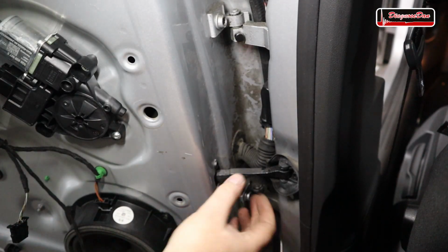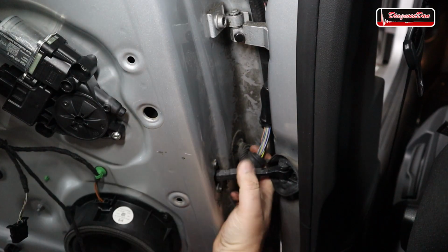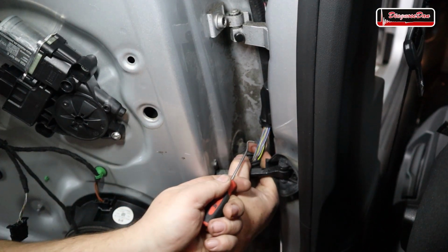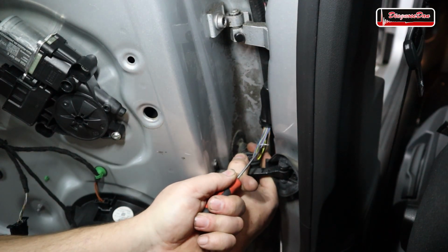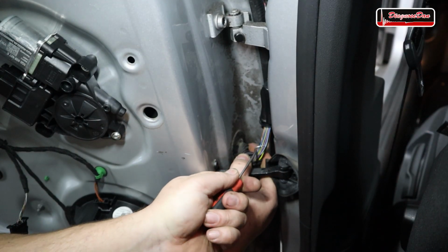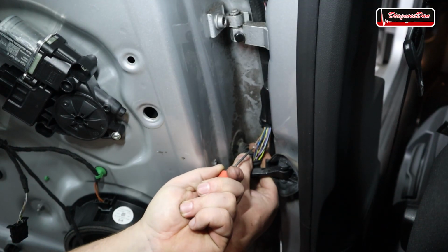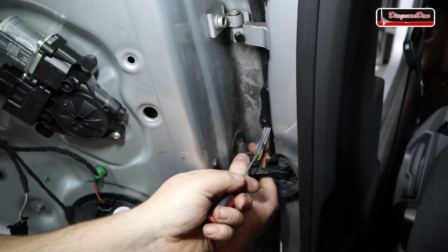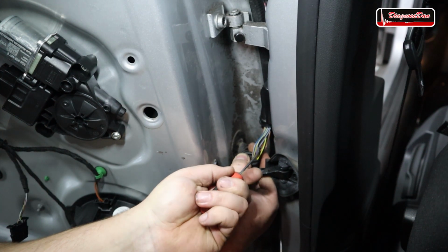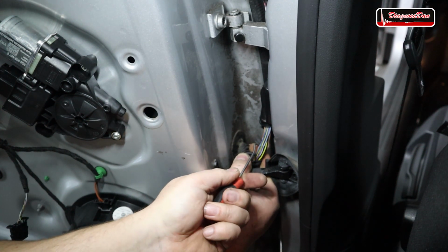Right now we're at the rear door. I already pulled the grommet down a little bit. Let's try to pull it down a little bit further. And again, we're going to pull those wires one by one with a hook, because broken wires in door hinges are very, very common. Again, the other shop has already checked this, but of course we're going to check it again just to make sure they haven't missed anything. Again, the wires look in great shape.